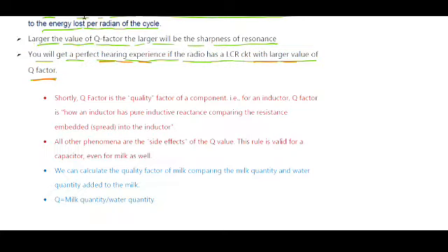Another interpretation of the quality factor is this one. Shortly, the quality factor is a quality factor of a component. For example, for an inductor, the Q factor tells how much pure inductive reactance the inductor has compared with the resistance embedded in the inductor.